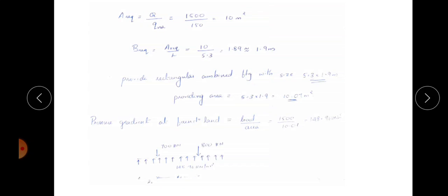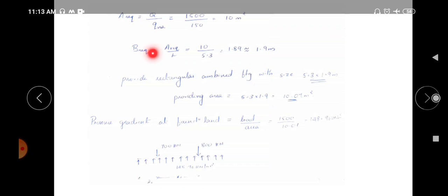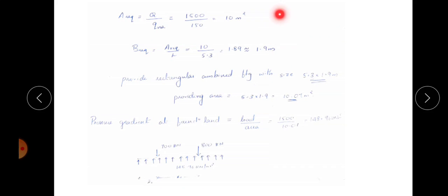It's very simple. First you calculate x bar by taking moment at A. So we have obtained x bar. In the second step, calculate x1 bar. x1 bar is equal to x1 plus x bar. Then the required length is 2 times x1 bar. And check whether the required length is greater than the minimum length. Then our design is okay. Then calculate the area. Okay. So from this area we can calculate the width. So this is the required dimension of the rectangular combined footing, and we can also draw the pressure distribution diagram like this. Okay, so I think it's clear.